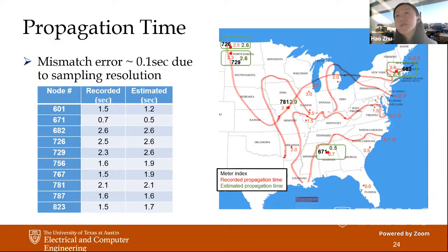So we have different models to describe the grid behavior to different levels. What I can say is that the initial response of this dynamic behavior is pretty much the same as the small signal response. But if we look at the recovery phase, like how much the frequency can go back to normal, that has other mechanisms, like control mechanisms, or area-based control mechanisms. So it's not fully described by this small signal analysis. There is some kind of mismatch if we want to understand the longer-term behavior, like 10 seconds after the events. But for the first few seconds, this small signal analysis is quite adequate.